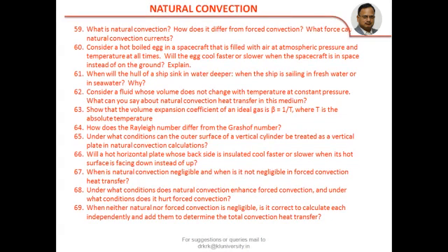So natural convection currents will set up effectively when you keep that deep freezer at the top position in the refrigerator box, so that the contents which we place even at the bottom get cooled effectively. Instead, if you keep the deep freezer at the bottom, cold air will not move up because it is denser than hot air. So uniform distribution of cooling is not possible in the refrigerator. Anyhow, you try to answer.